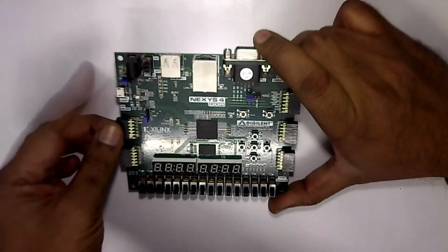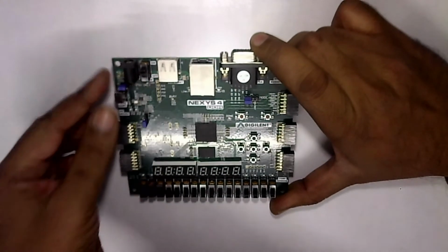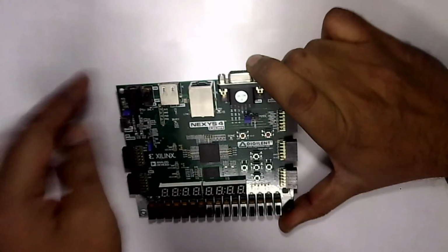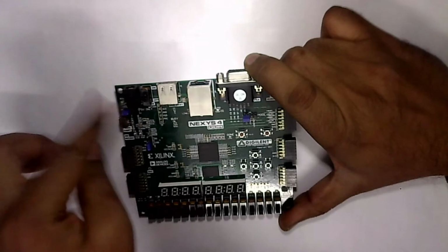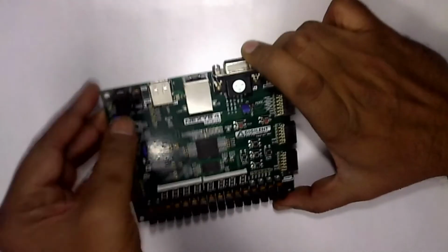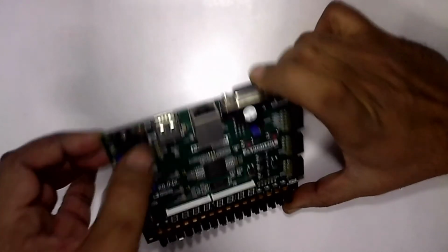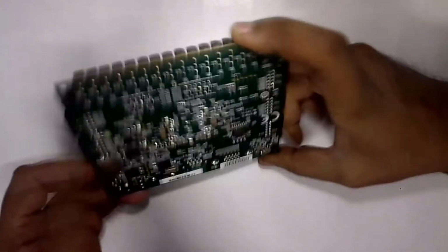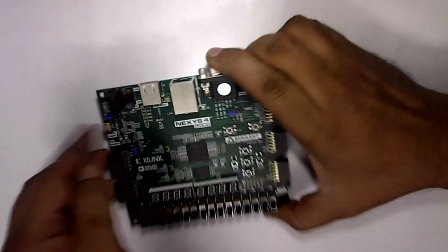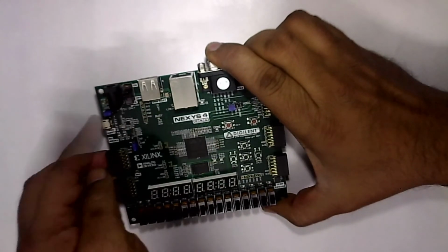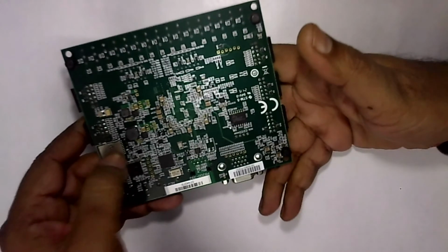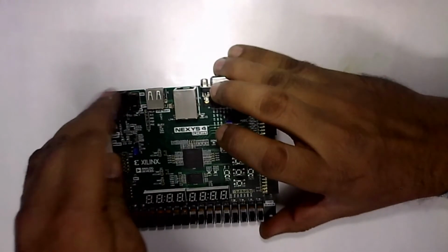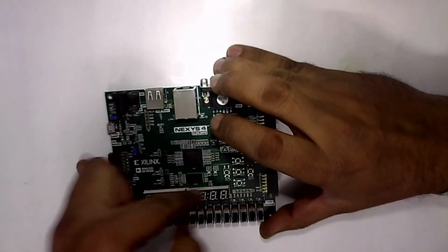Directly you can hook it up to the USB port of a computer, and then you can directly write the bit stream to program this FPGA. And the next thing what you see over here is this connector. So you can also have the code in a micro SD card over here, right? So you can either get the bit stream to program the FPGA from here, or you can also have a micro SD card. So whenever you power up this board, the micro SD card is going to provide the bit stream